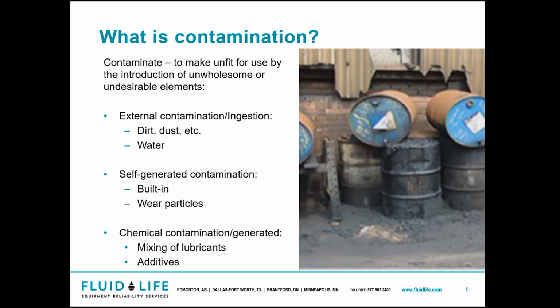So the biggest thing when it comes to oil and starting out is cleanliness and contamination control. They are going to be the most important aspect of proper lubrication for long equipment life and lifelong lubricant life. If it's dirty going in, if it's not good or full of dirt, full of water, any of those kinds of things, you're basically starting in a deficit already. So making sure that we have everything aligned and good is going to be greatly beneficial.